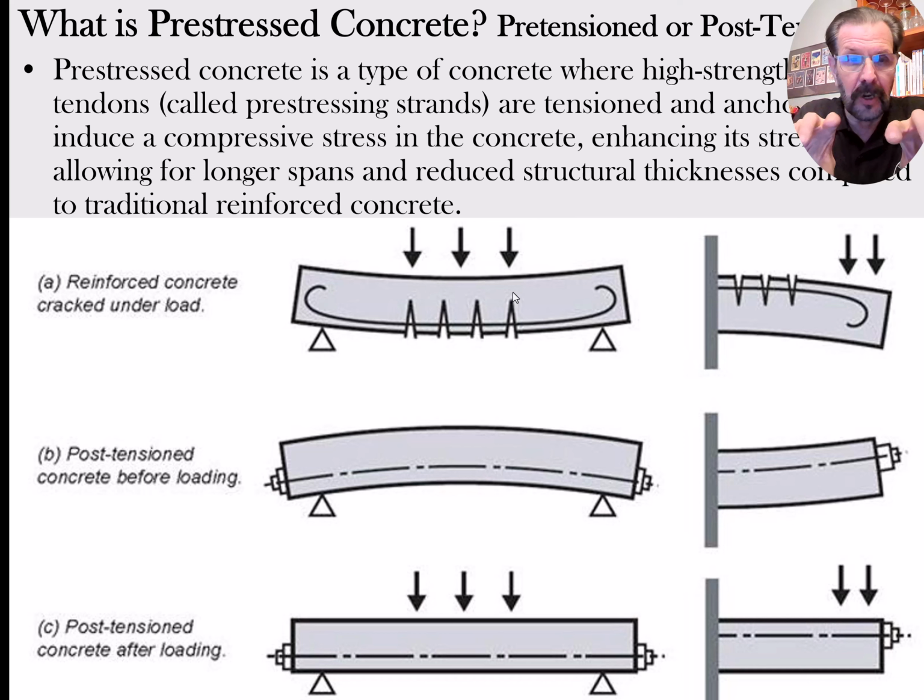You need a certain amount of concrete around each piece of rebar in order for it to develop strength and bonding and everything else. And so you can only go so far with rebar. And that limits the size of your beams or how much load they can carry. So over on the left side, we're looking at the idea of where the rebar needs to be. In the top of the beam, when it's a cantilever, when it's dangling out. But predominantly, the rebar needs to be down in the bottom of the beam when you're going from point A to point B, like we have in this main beam that I've got my cursor around.